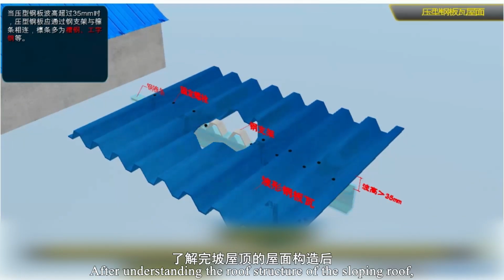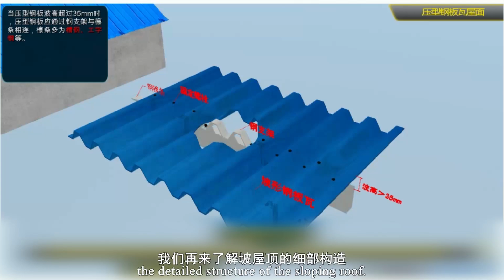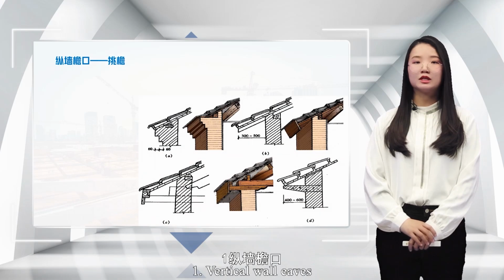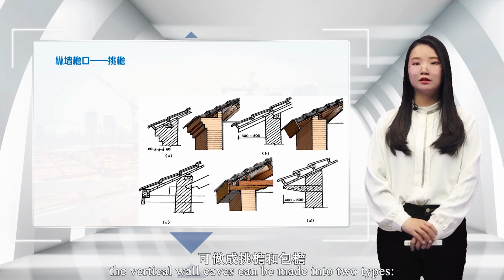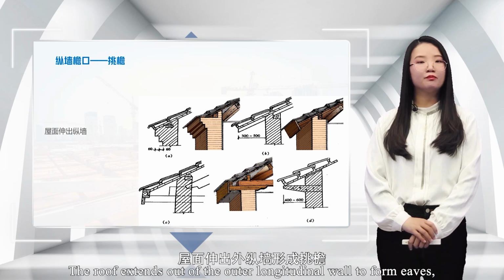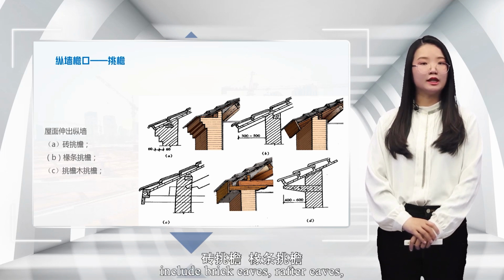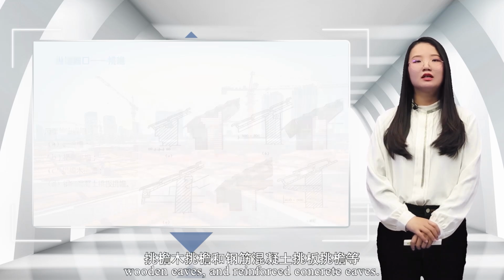After understanding the roof structure of the sloping roof, let's now delve into the detailed structure of the sloping roof. First, vertical wall eaves. According to requirements, the vertical wall eaves can be made into two types: overhanging eaves and enveloping eaves. The roof extends out of the outer longitudinal wall to form eaves. And the construction methods of eaves include brick eaves, rafter eaves, wooden eaves, and reinforced concrete eaves.